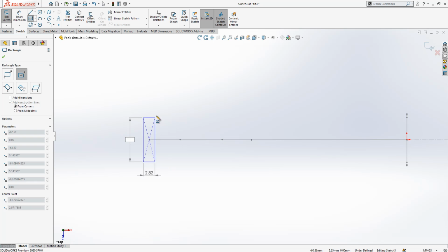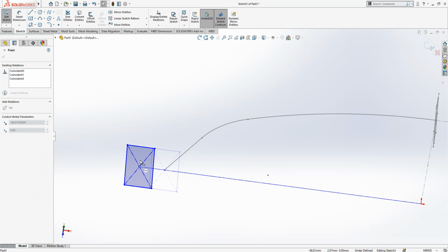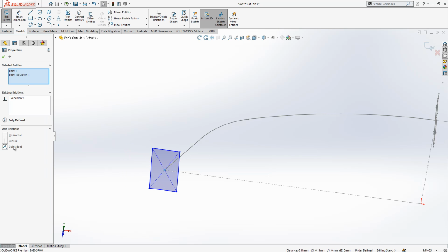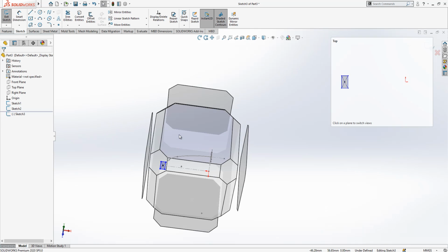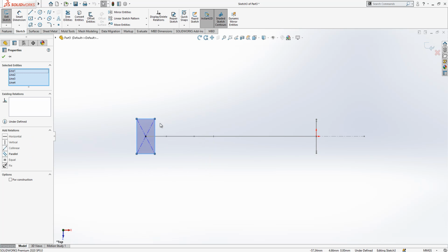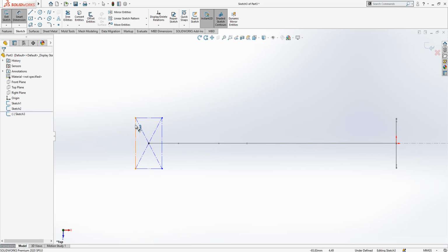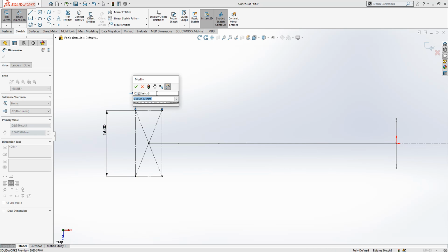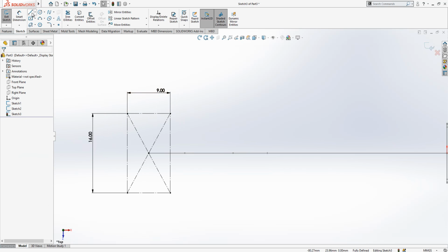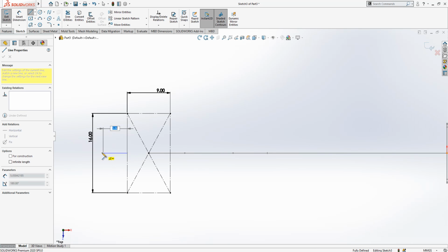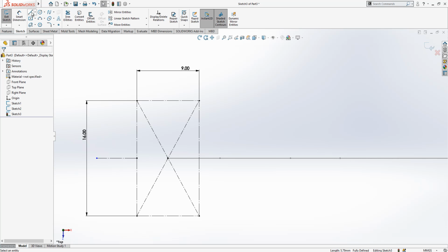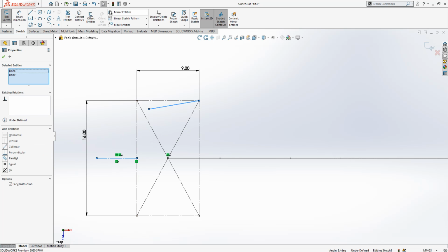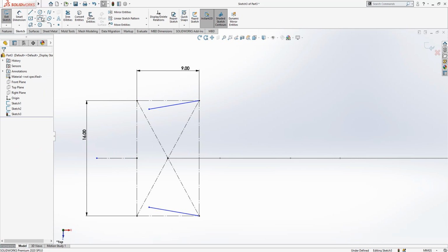So again a rectangle, but to be able to show we are in the right center, I'm just moving it. Control is pressed and I make coincident between 2 points. Right click, select chain, and now everything will be construction geometry. Now it is 16, depth is 9. It is convenient to have one construction geometry to be able to make a mirror again, something like this. And I select them, Control is pressed, and make mirror.